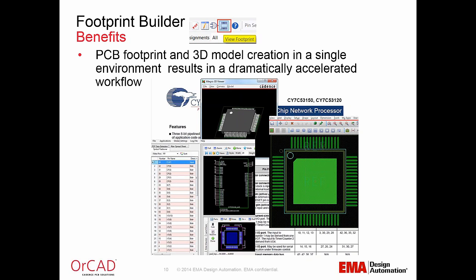So OrCAD Library Builder ships with 100% of the SMD packages that are defined in the IPC 7351 spec, plus through-hole devices and connector templates. And users can also create footprints per vendor recommended land patterns. So not only is it an IPC calculator, but if you need to customize that part per a recommended land pattern from the vendor, you can customize that part as well.